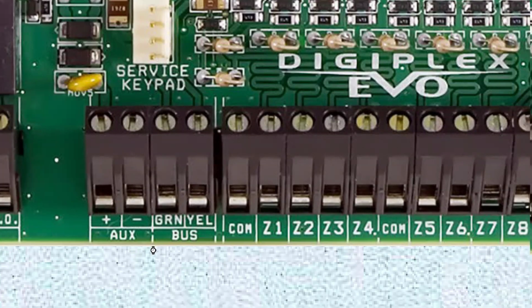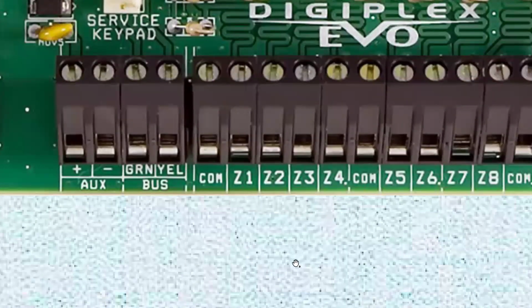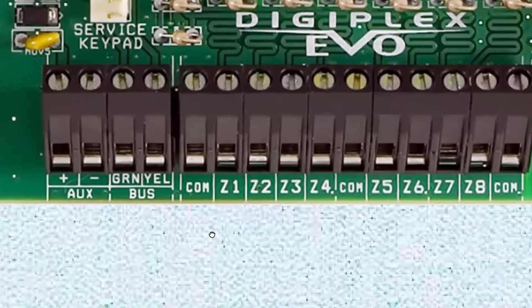So you're going to get a bunch of wires with the power to whatever devices, and you're going to get all the red ones and all the black ones combined, and you're going to make a pigtail, and just tap this one here and tap the other one here, and there you go. You have power provided to all the devices. You can disconnect one and put the ohm meter in series and say, okay, well, it's draining so many amps, and you're going to look at the specifications of the board. Is that supposed to be providing that many amps, the overall equivalent load of the whole thing draining? All right, but I don't want to repeat myself.